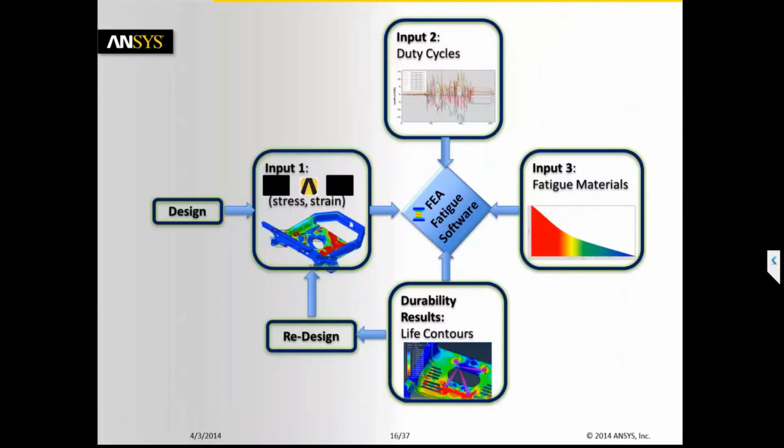So coming to here, typically we will have a design, and then we prepare the FEM model, where you can take the material data, and then, based on the material data as well as the loading conditions, either you can assign a cycle in the FEM here and repeat it in the fatigue, or you can assign a unit load and then map it in the fatigue.